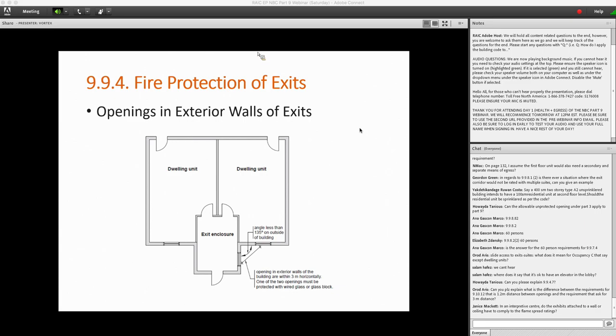Okay, so I'm back. So, clash with the guard requirements. There are exemptions in the code. When you read 9.8.8.1 sentence 5, it discusses the exemptions that windows need not be protected in accordance with sentence 4, which is where you may require a guard, where the window serves a dwelling unit that is not located above another suite, and where the window serves a house with a secondary suite.